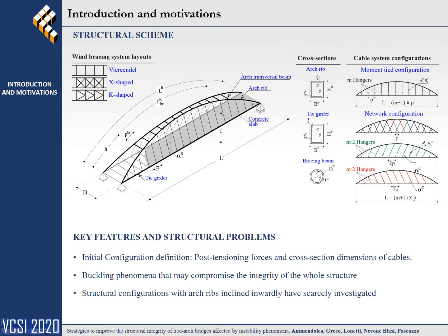The structure of a tied arch bridge is composed of two arch ribs which sustain a lower deck by means of several anchor cables. In particular, the deck ties the arch ribs' extremities together, thus supporting the arch horizontal thrust. The anchor arrangement classifies tied arch bridges.